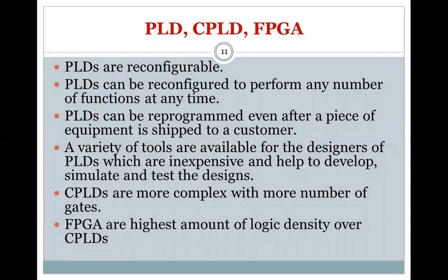Then PLDs offer customers a wide range of logic capacity, features, speed, voltage characteristics. PLDs can be reconfigured to perform any number of functions at any time. That is another advantage. PLDs do not require long lead times for prototypes or production parts because PLDs are already on a distributor's shelf and ready for shipment. And PLDs can be reprogrammed even after a piece of equipment is shipped to a customer. That is another advantage. A variety of tools are available for the design of PLDs, which are inexpensive and help to develop, simulate and test the designs.